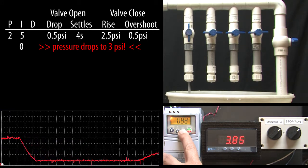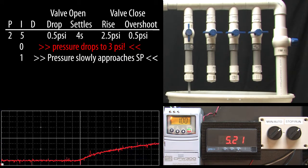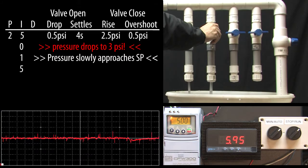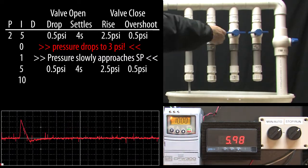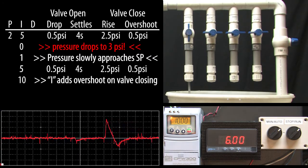I defaulted to 5, but what happens if we set it to a 1? Well, look, it's summing all of those little errors and slowly pushing our process towards the target. I'll speed that up so we don't have to wait, and it took almost a minute to get to our 6 psi target. I'll change I back to the default 5, open and close the valve, and sure enough we get the faster response we expect. Okay, let's double I to 10 and open and close the valves. Look, the I term seems to be the one that's impacting the overshoot on the valve closing. And since we were doubling it every time we doubled P, it kept getting worse.